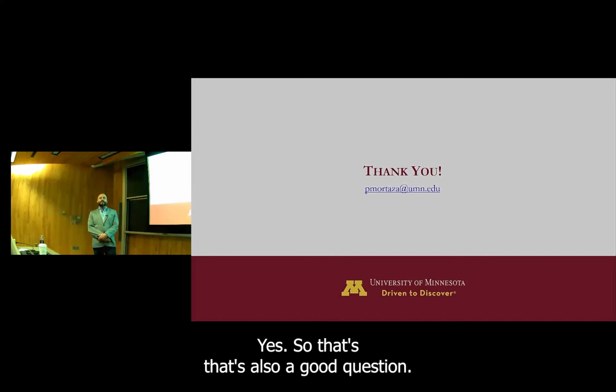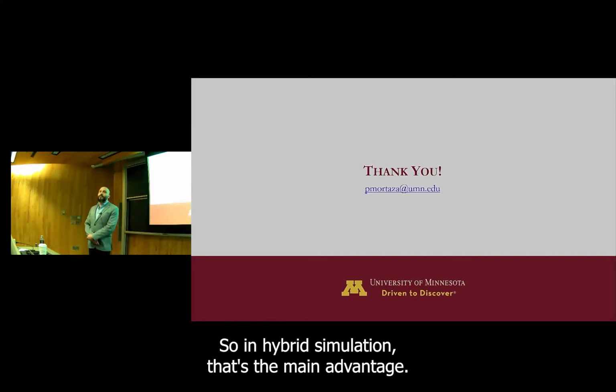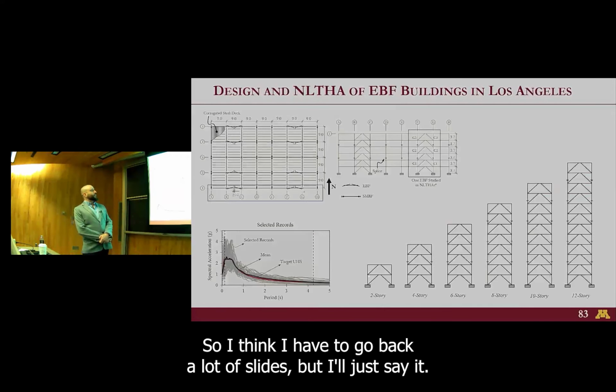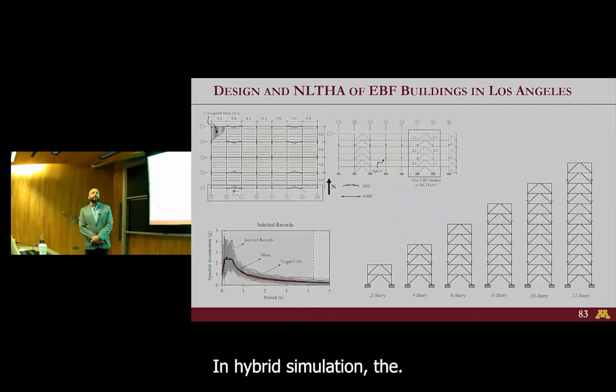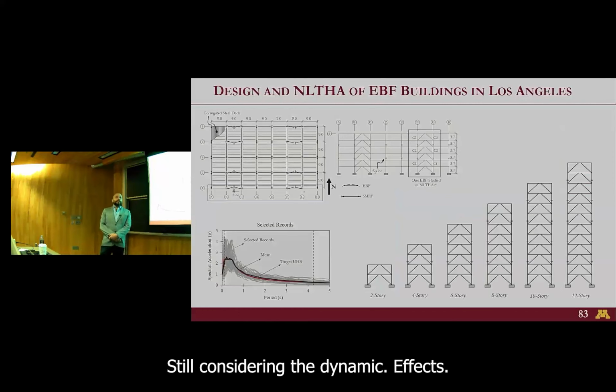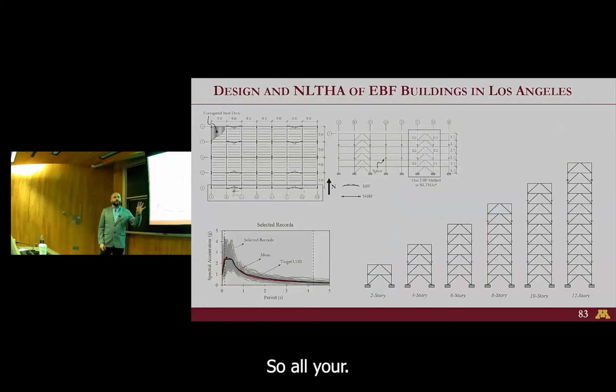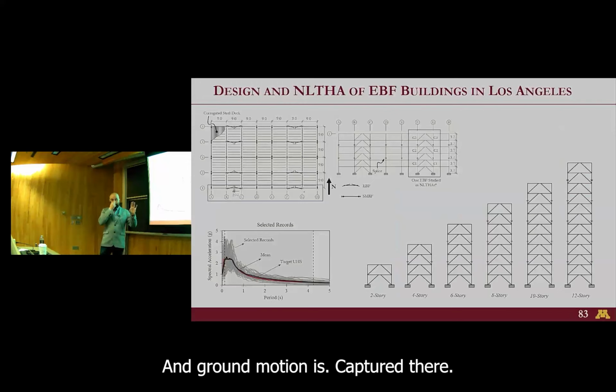Yes, that's also a good question. In hybrid simulation, that's the main advantage. I think I have to go back a lot of slides, but I'll just say it. In hybrid simulation, the good part is that you're still considering the dynamic effects by doing dynamic integration in your integration module or your numerical model. So all your accelerations, velocity, and ground motion is captured there.